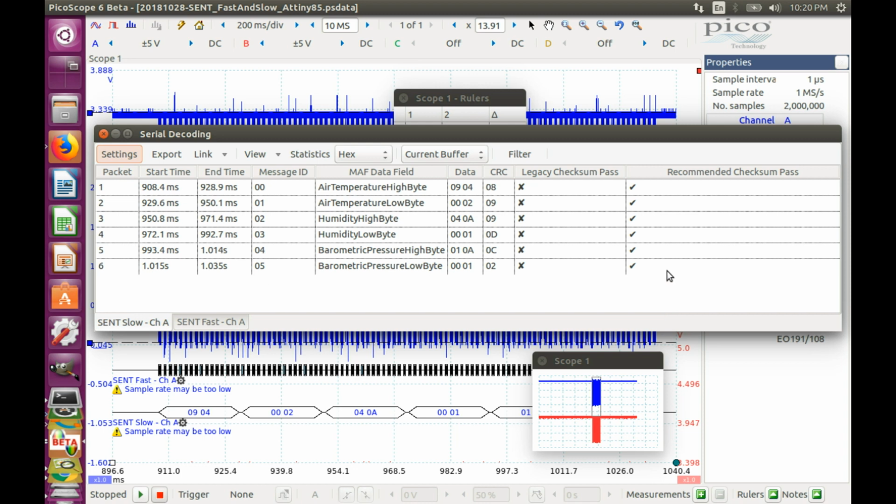Checksum passes for all of them, which is good news for us. And the data for message ID 0 is 94. For message ID 01, it's 2. Remember, these are the message IDs for ADC channel 3, and this represents the low byte, and this represents the high byte for it. So the number that's reported is 294. Does it remind us of something?